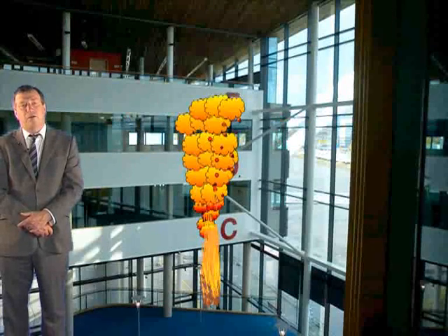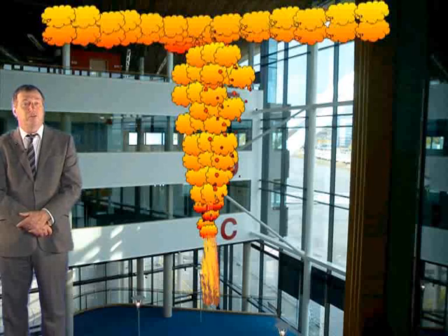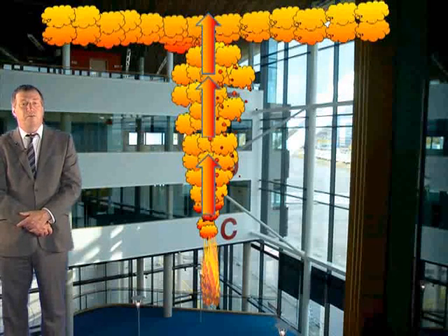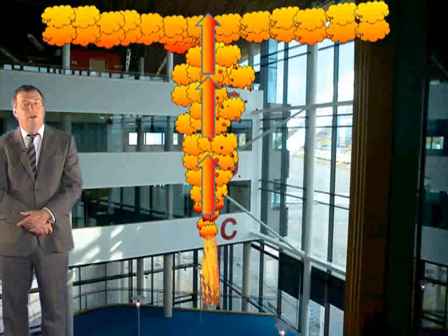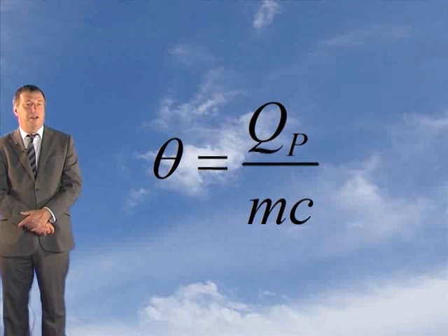Now we shall look at how to determine how hot the smoke is, and we shall see that this depends upon the rate at which smoke is produced. If we know how much heat is going into the smoke layer by way of the plume, and we also know how much smoke is going into the layer by way of the plume, then we can use a simple formula to derive a figure for the increase in smoke layer temperature above ambient temperature. The formula is shown here.